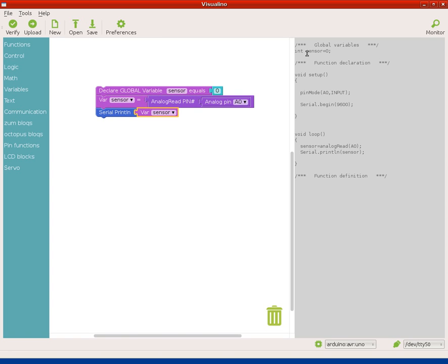So that way we are telling the microchip to book some memory space for that kind of numbers, and not any bigger or smaller. And then there, in the setup section, we got the A0 declared as an input, which actually shouldn't be necessary for an analog one.